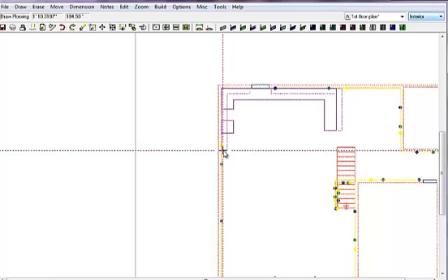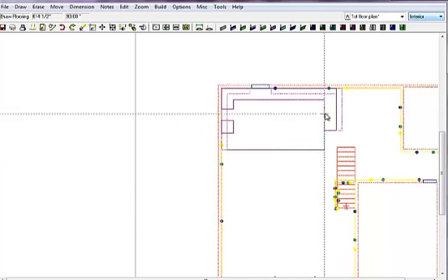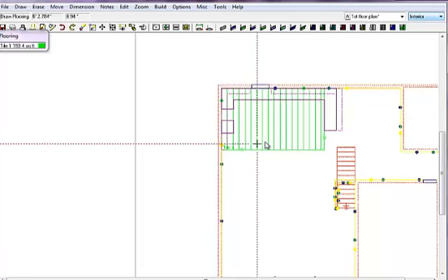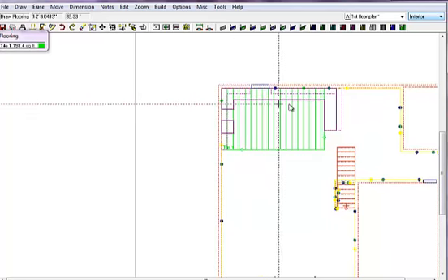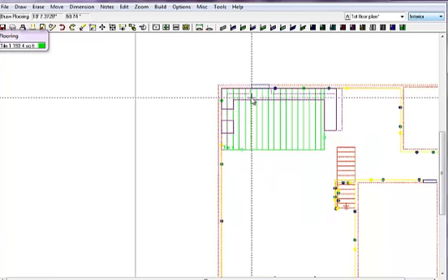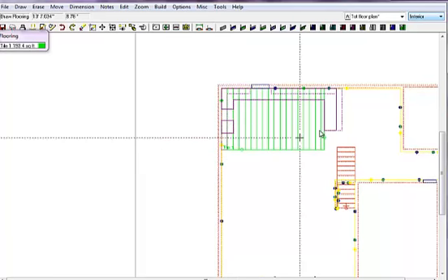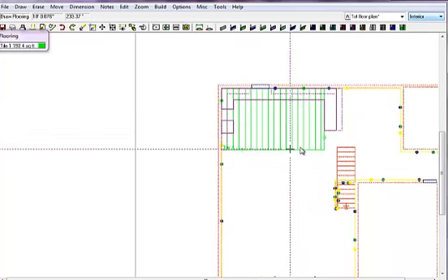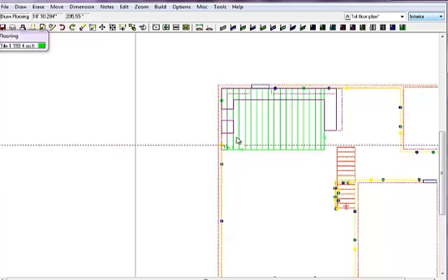Oh, it wouldn't let me do it because it wasn't a closed area. So I'm going to do it one more time. I'm going to do it a little bit more simply this time. I'm going to go through, across, around, and back, goes in the area. So now that is all tile, and in this case it's actually put the tiling underneath the kitchen cabinets, which is doable, maybe not as likely. What I could have done was to do the area all inside of the kitchen area, and then done a little piece just to extend that through to here.